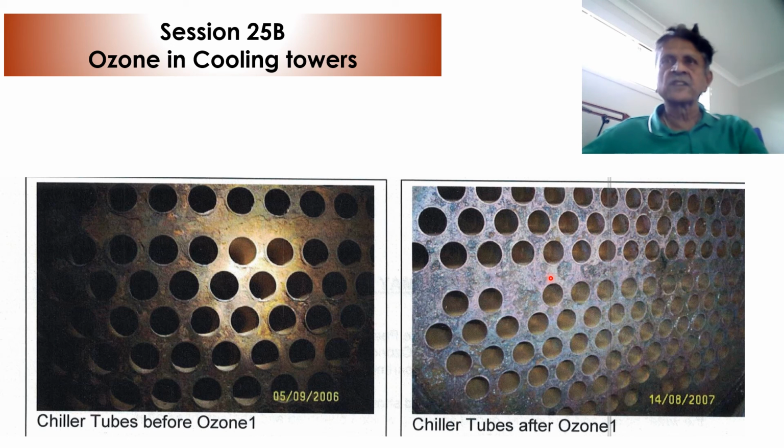Also, like in Australia, there's a statutory requirement that you have to clean the towers every 6 months, but if you apply ozone, you can do that once a year. So you do save time in labor, save time in chemicals, and save time in downtime, because cleaning up a chemical treated tower will take twice or 3 times longer than cleaning up an ozone treated tower.